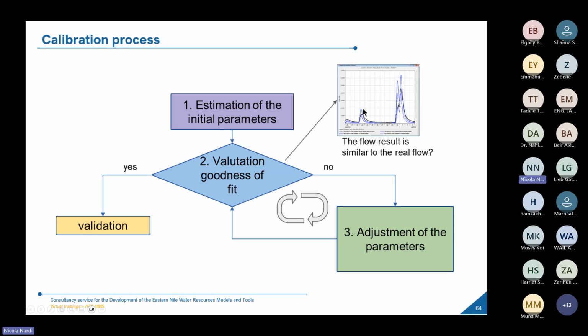What will happen is that once you open the results, you will have also another hydrograph, that in this case is the one composed of small segments of blue. And you need to check if my hydrograph can be comparable to the one observed, if our results are good enough to be considered as a representation of reality.